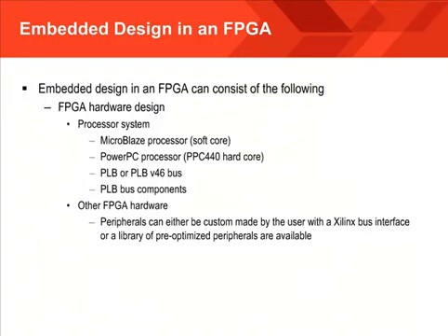Typical embedded systems are tuned for low cost, minimal power consumption, relative speed, and minimal FPGA resource utilization. As you may know, many customers like to store their software code inside of the FPGA block RAM. The caveat to this, however, is that there is a limited number of block RAMs inside of the FPGA. But this will depend on the device family and, of course, the density of FPGA you decide to purchase.